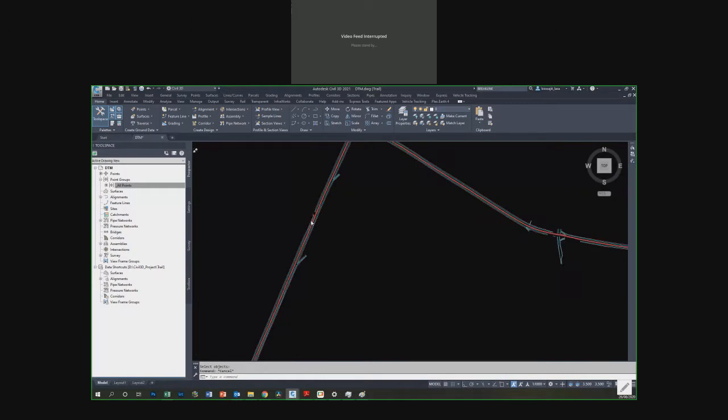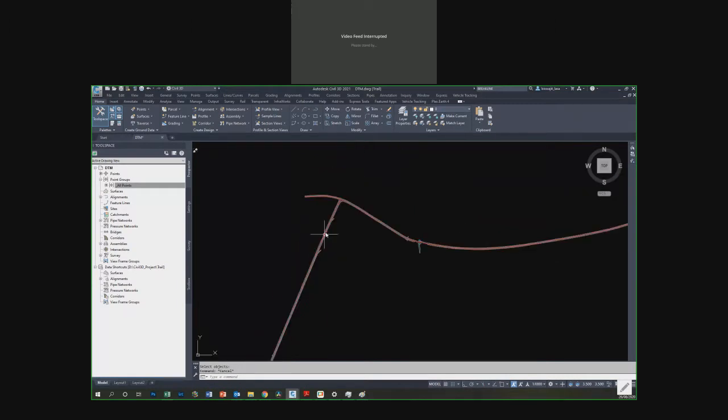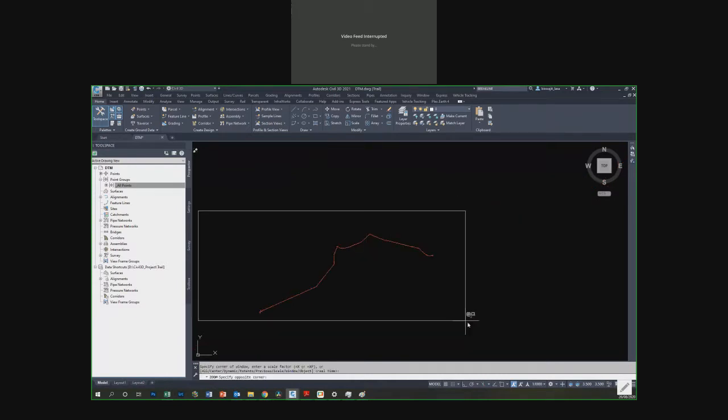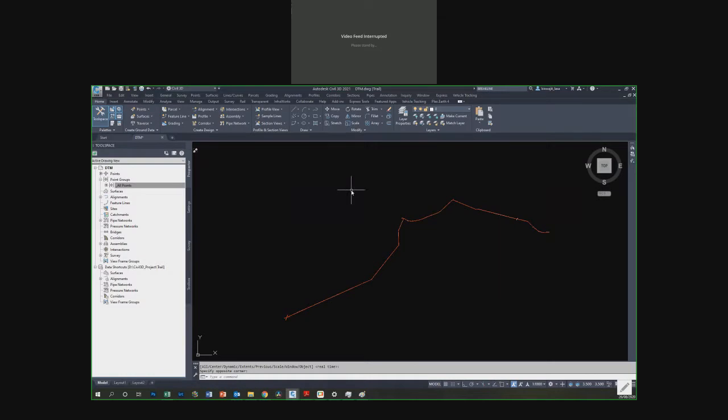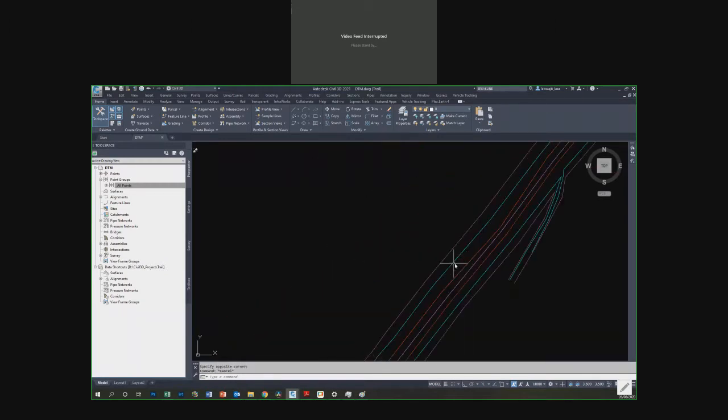Now you need to make sure that we always try to have a 2D drawing. It's up to your wish if you consider this survey data, but then you need to check the entire survey data, that no line should have a zero elevation. If you are on that area, you will know the probable range of your elevations. So if you see anything which is an outlier for that elevation range, then you can exclude it, or you need to check all of these lines. We are going to use a proximity one. So I'll change everything to a 2D line.